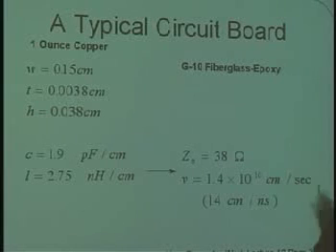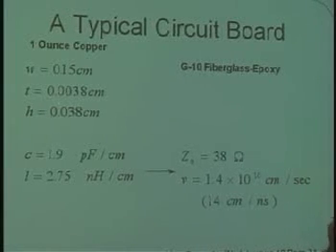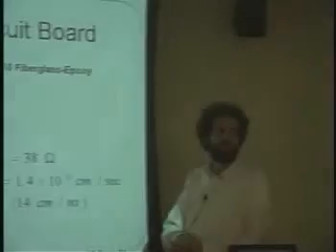If the wires were out in space and the wires were very, very thin, then it would be at the speed of light, but they aren't. Okay? It's because the capacitance of the circuit boards is more than free space is, and the inductance of the wires is also more. The resistance to change is greater, so it takes longer for the signals to propagate. Okay, I think that's probably it.